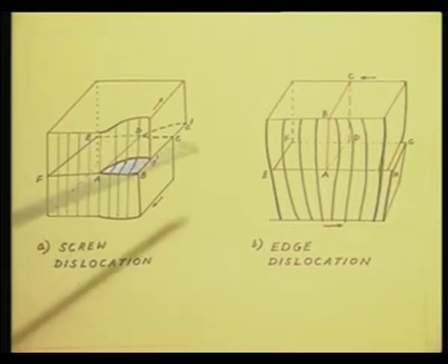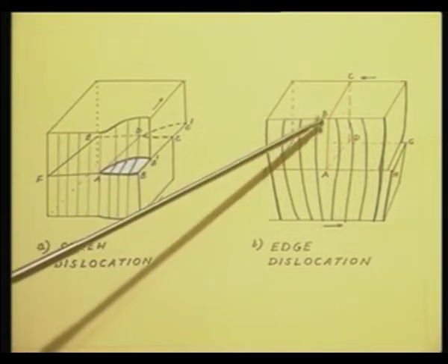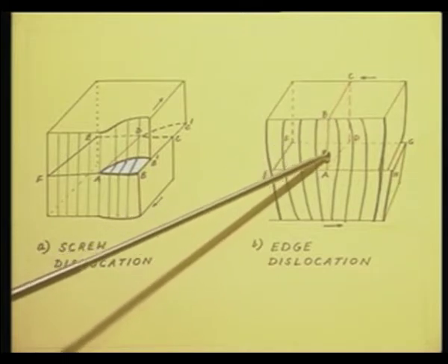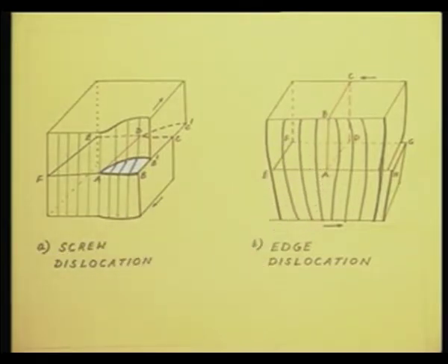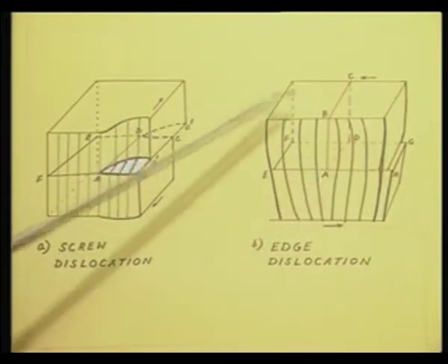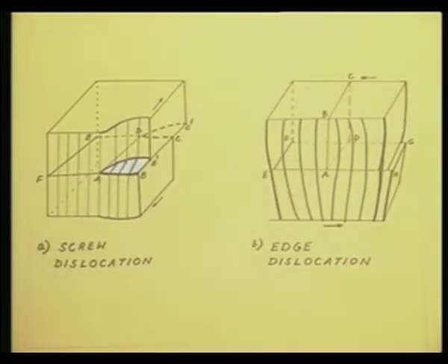See, if you view it in 2 dimensions, then all these black and red lines actually signify the array of atoms. Atoms are placed along this array. So, what you have done is you have created an extra half plane, it is not continued throughout the crystal. Only in the top half you have created an extra half plane of atoms. This is called an edge dislocation, extra edge.